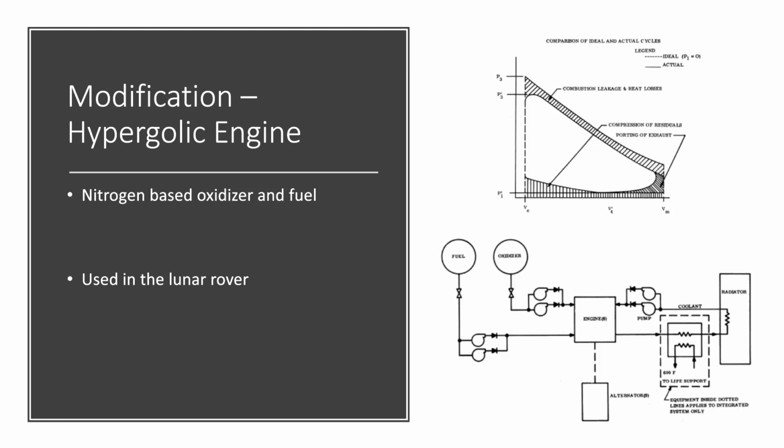Through what is called super insulation, when these tanks are full, the requirements on the temperature aren't an issue and are naturally maintained. However, as these tanks begin to empty, some of the work has to be diverted to the tanks to maintain their temperature through temperature control units, reducing the overall efficiency. Other issues include that the hydrazine is both corrosive and toxic, making it difficult to handle, and all of the parts have to be treated so that it doesn't damage them over extended use.